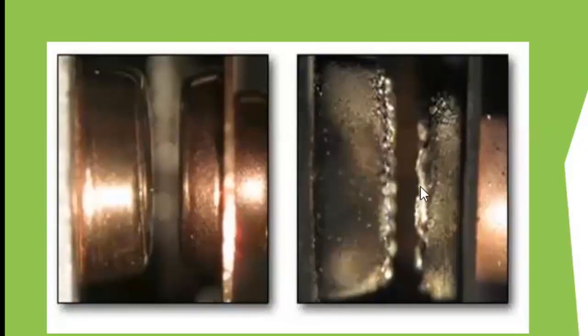So if your contact is made of copper, you find the deposition of copper oxide, which are heavy insulators, or if it is aluminum oxide on the contact. And those aluminum oxide or copper oxide, or rather all oxides of metals, have very high insulating capabilities.